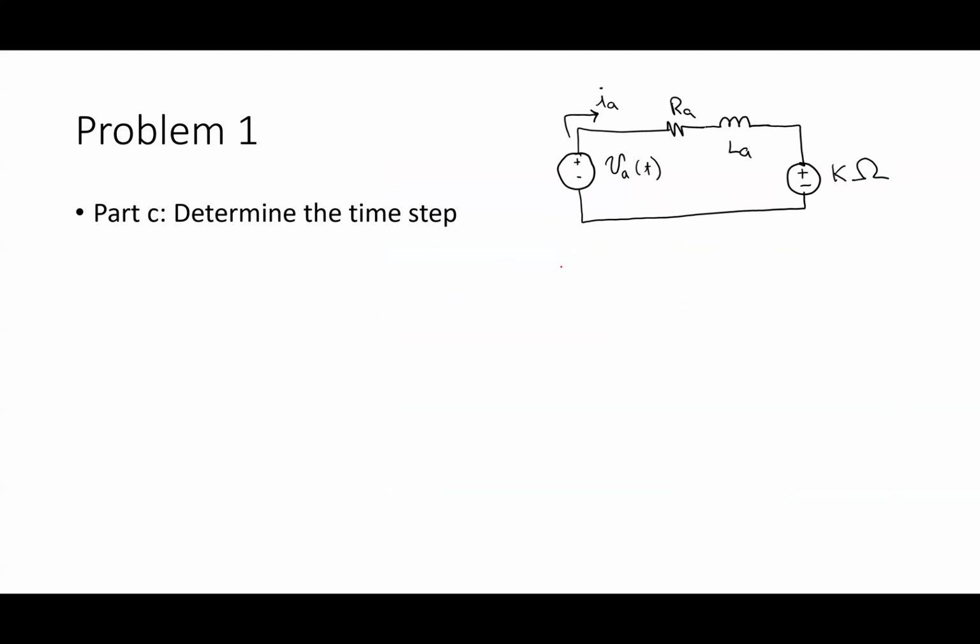There's basically one where I have the electrical equation. So if I did a KVL around this loop, I have V sub A equals I_A R_A plus L_A dI_A by dt plus K omega of t. So this thing here I talked about last time. This is basically a dependent source inside the motor.